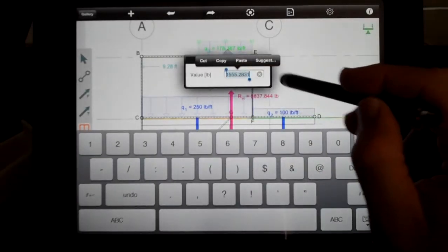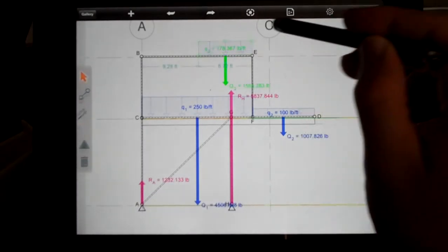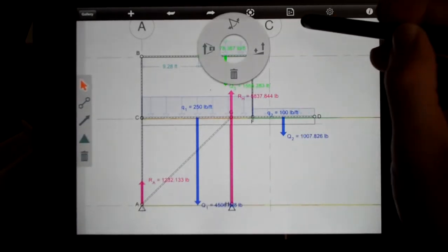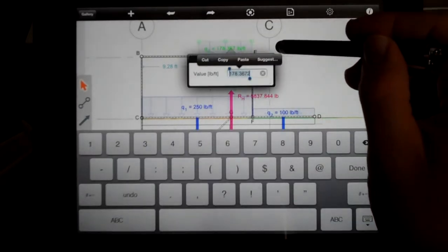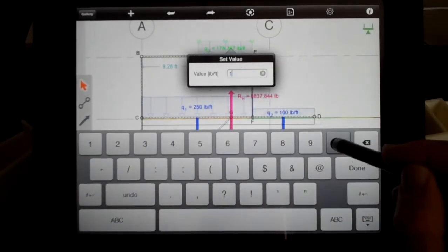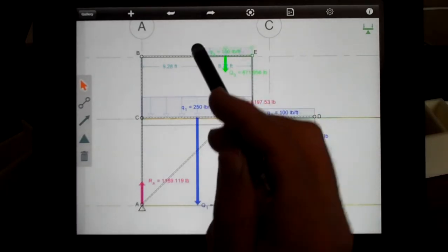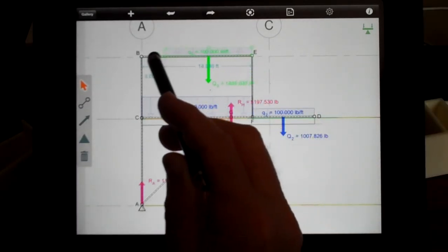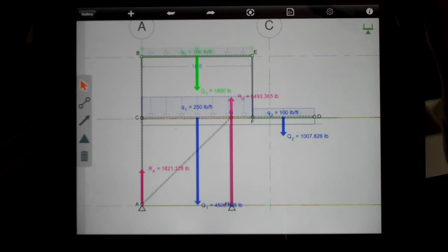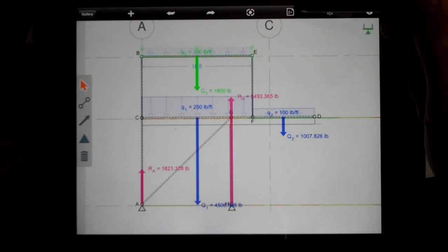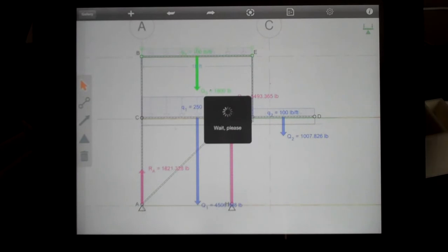So again, to bring up that number, I'm just clicking on the pounds per square foot icon. There it goes, pounds per square foot. Just having a little trouble selecting that particular member. Then I'm going to click on the lower grip and bring that across. And so essentially, that builds all of the reactions for this entire case. And the next thing I want to do is actually create the calculations for all of the members. So I'm going to click the Calculate button at the top.